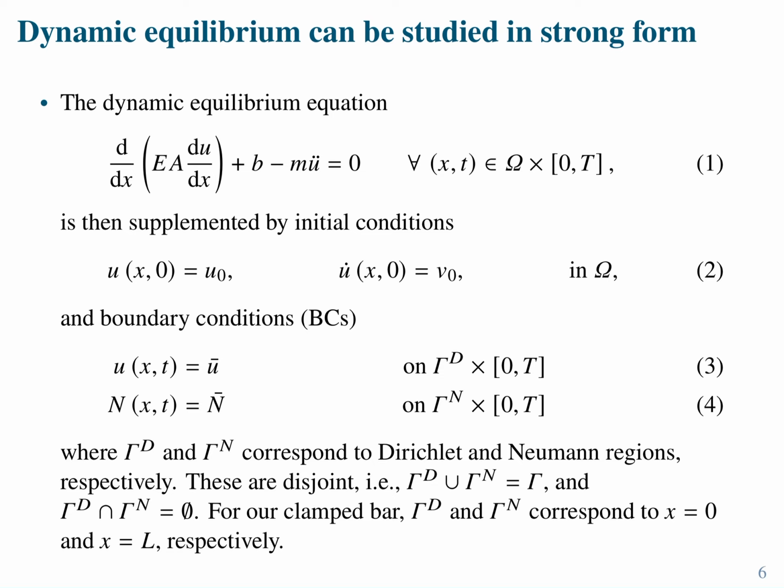And then the boundary conditions, what you see, the first one is we're prescribing the displacement. Gamma D here is going to be the portion of the boundary with Dirichlet boundary conditions, or essential boundary conditions, or displacement boundary conditions. So in this case, I'm prescribing the left of the bar to have 0 displacement. So that is a strict constraint on the bar. The bar cannot move anywhere at that point, right? So this is our essential boundary condition.